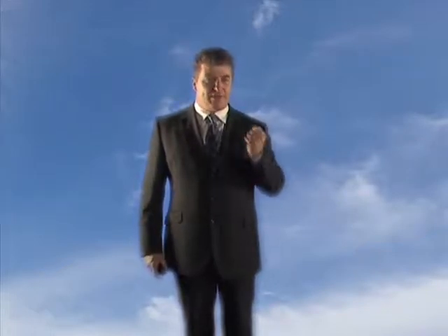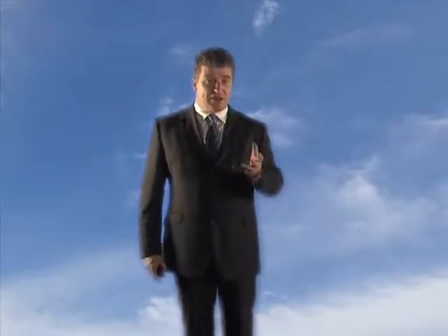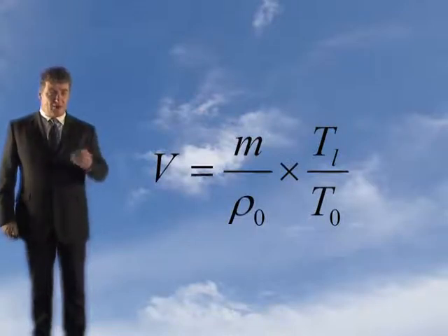Now next, because we're looking at mechanical ventilation, you don't have to determine the aerodynamic free area of vents in the area. You have to work out the volumetric flow rate in each reservoir, and this is based on your design fire size. To determine the volumetric flow rate, you use this formula here.